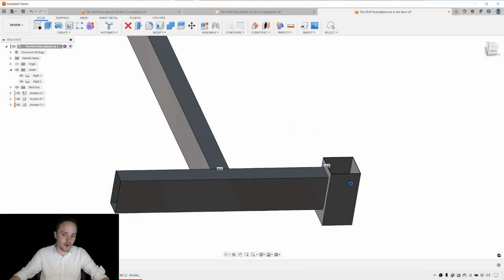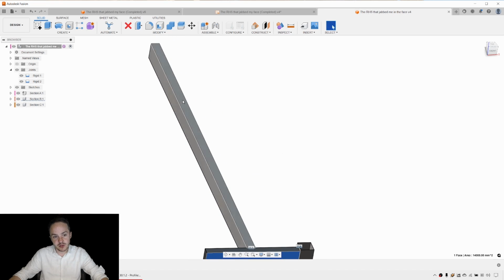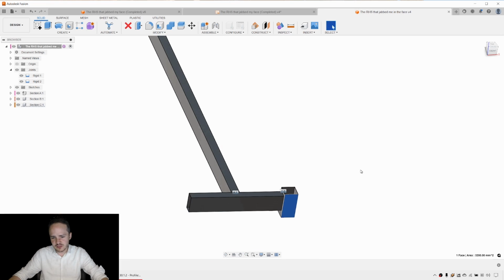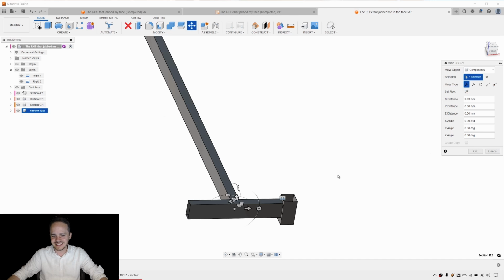And we're going to quickly do the remaining components. So let's go ahead. We are going to make a duplicate of this rectangular hollow section and put it on the other side. And then we're going to make 4 of these legs. So we like to be lazy. Rather than creating a whole new component and defining its unique characteristics, we are going to copy and paste. Let's go ahead and select section B here. And literally Control C and Control V, copy paste.